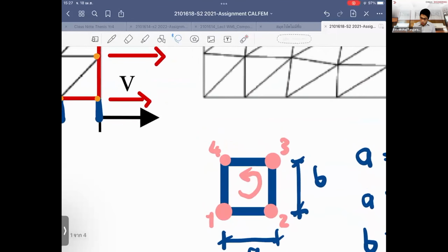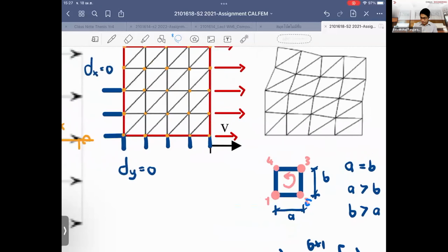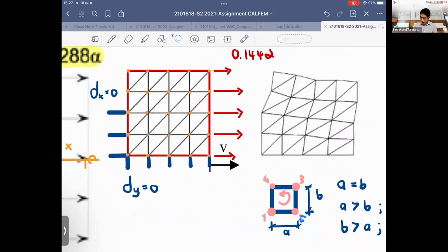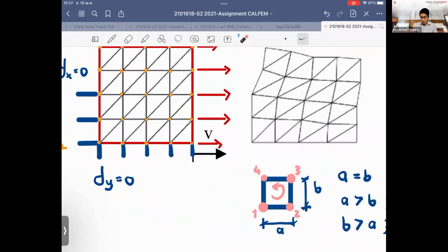So that's why we use an isoparametric mesh rather than a quadratic mesh. The quadratic is a 4 node, but you don't scale them, so you don't use what's called the unit length of the element you're looking at. So if I stick to the pattern when I want to connect the nodes, this is the connectivity. The connectivity is when I start to tell the program, or I start to construct the matrix, according to the node where I start from. I start from node 1, go to node 2, node 3, 4, and finish at 1, right? So I close up the node.